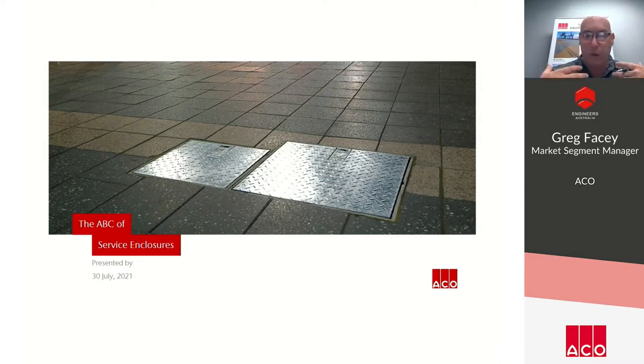Today in the industry, there is a wide range of trafficable cable enclosures in various types of materials, including non-conductive plastic, cement concrete, GRC, which is a glass reinforced concrete, and polymer concrete. There's also a wide choice of lids and access covers to meet the anticipated load requirements of the project. The covers can vary from non-locking and standard locking to high security designs to meet specific client and government requirements. Cover and frame systems also provide secure protection to cable enclosures and enable decorative floor finishes to be maintained with minimal interference.